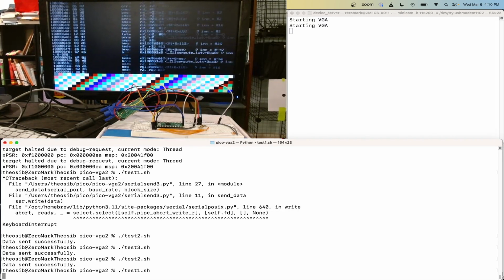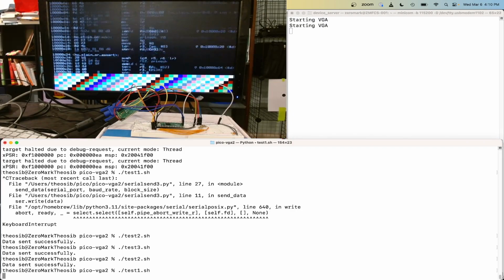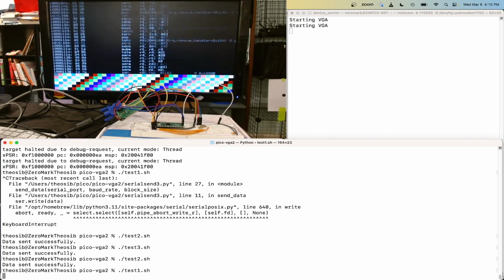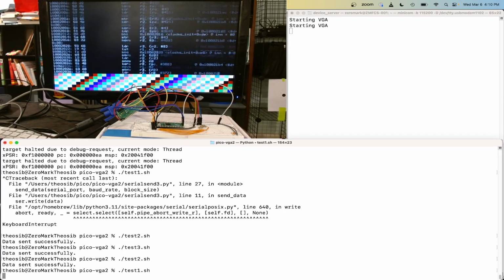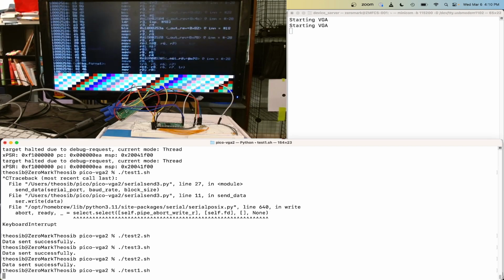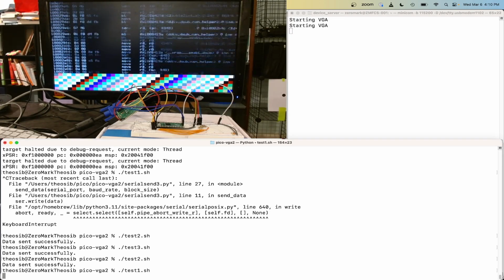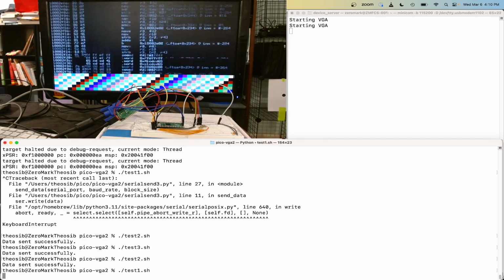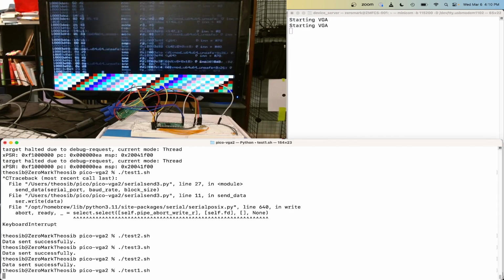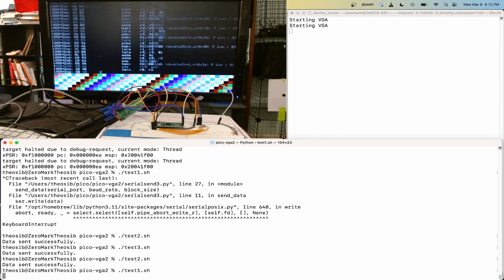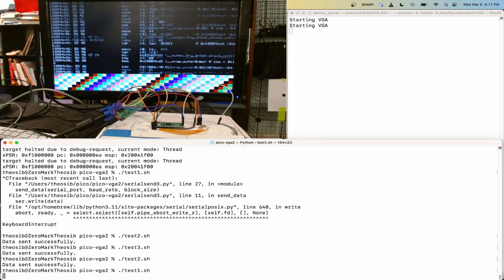I have a VT102 terminal emulator that I wrote like back in '99 that I managed to find on SourceForge still. So I went ahead and snagged that and re-uploaded it to GitHub. And that's being used to do this terminal emulation. So basically, I'm dumping data to the serial port, which at the moment, the Raspberry Pi thinks of as its console, like its input and output console. So it's basically doing get char on the console and then sending it to the terminal emulator.